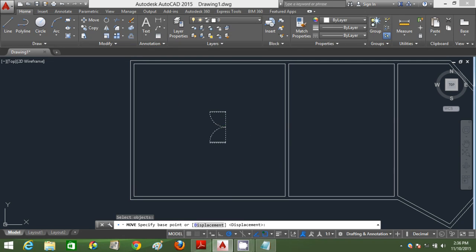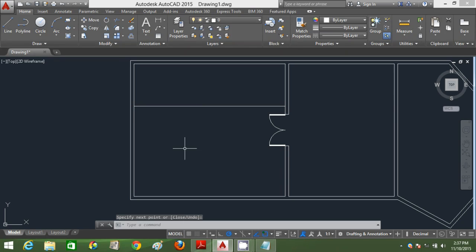Now we're going to move it to the midpoint of this wall. Wait until the object snap appears and click on it. I'm going to set the boundary of that door. Select those two lines first before trimming. Type TR and enter twice and trim out the unwanted portions. I'm going to mark one reference line here by 500 mm and draw this line to create the executive's office.